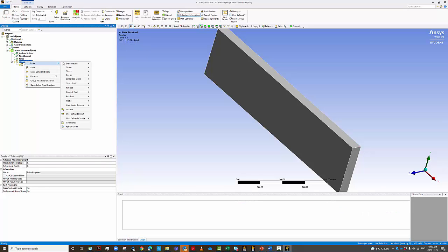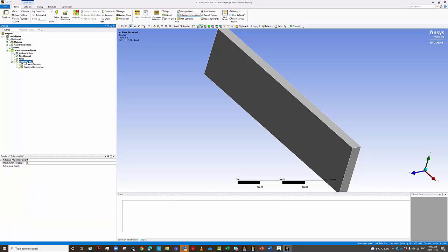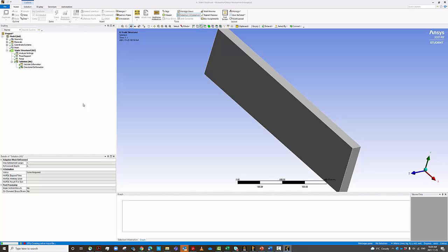Let me go to the solution, and let's okay, directional. Then I'm going to select the deformation in the y-axis. Right? Okay, and then of course you can insert other things, but I'm just going to look into the deflection in this area as my criteria. So let's go and solve. Solution quickly. That's why I selected only one of these loads.